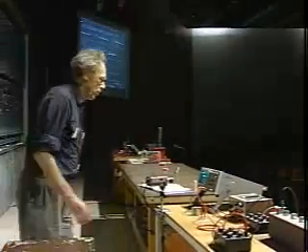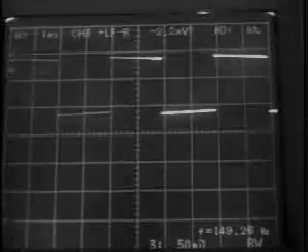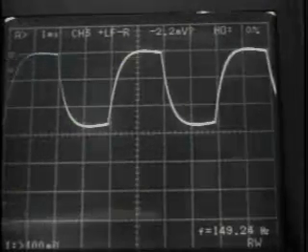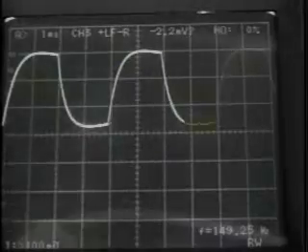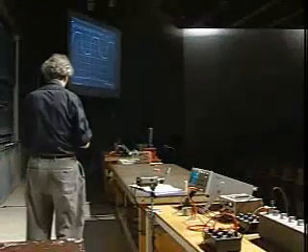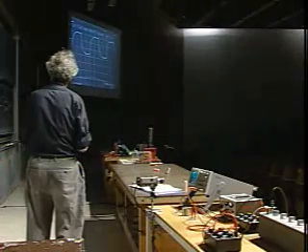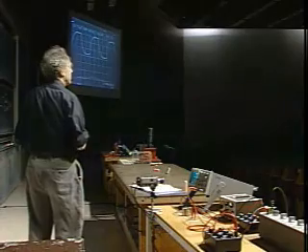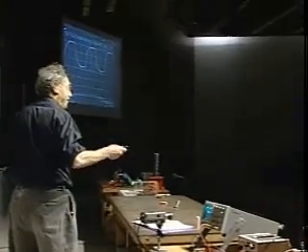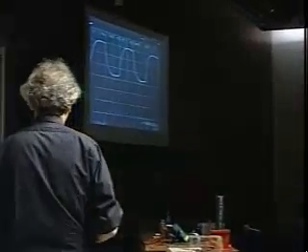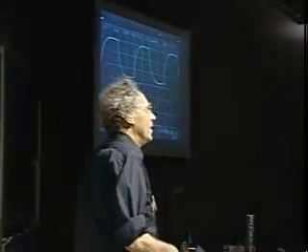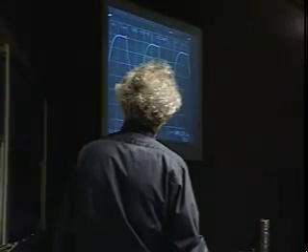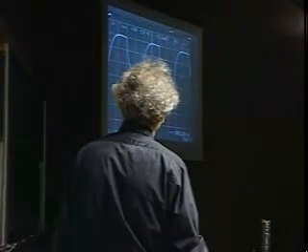And now I'm going to show you the voltage over the capacitor, and I will take the other one out. And here you see indeed exactly the image that we discussed. So you see early on the charging of the capacitor, and it reaches effectively the maximum value. You don't have to wait infinitely long. We always say infinitely long, but clearly if you wait 3 or 4, 5 times RC, then you're almost there. And then here, I'm going to switch it back to position 2, and you see it's discharging.